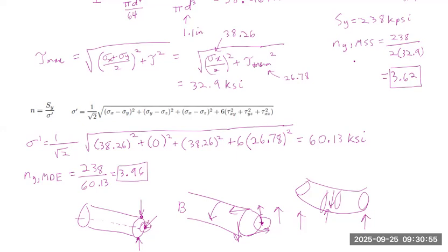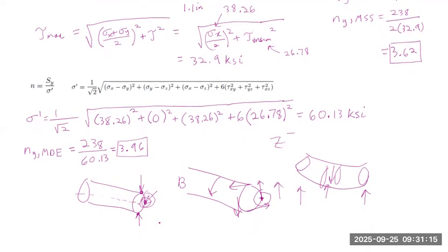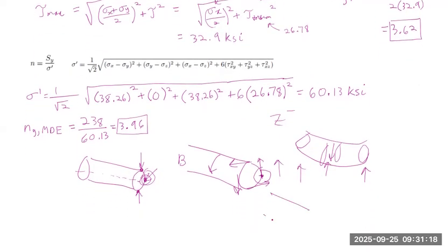And the maximum transverse shear stress typically occurs at the neutral axis of the beam, which is why we have to consider our Z minus face over here, the right face, because it's at the neutral axis. Transverse shear stress looks something like this. It is drawn as such: smaller arrows from the top, with a parabolic distribution, and the arrows increase, and when it reaches the center, the transverse shear stress is the largest.